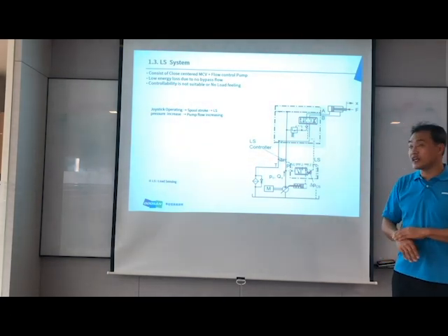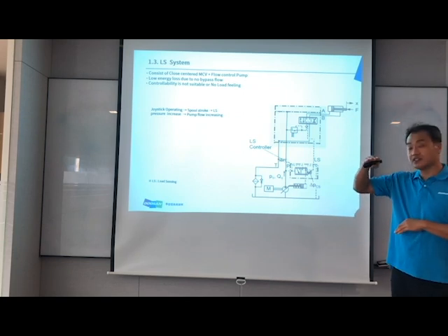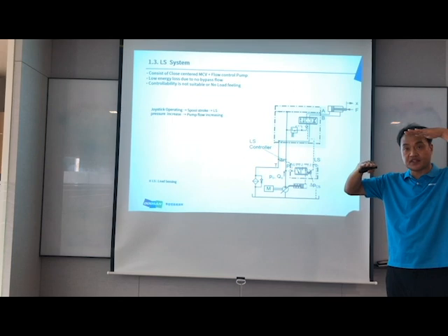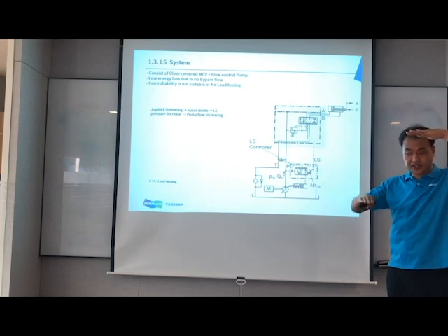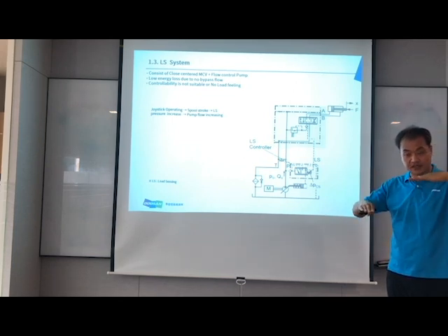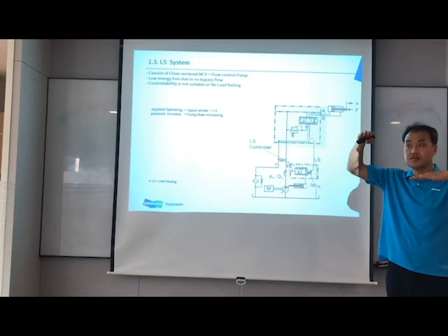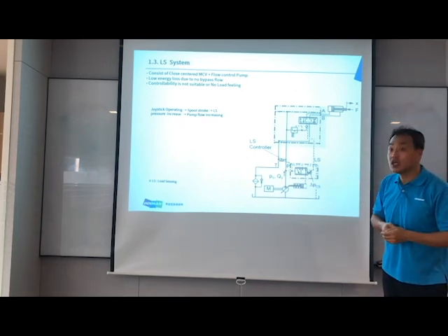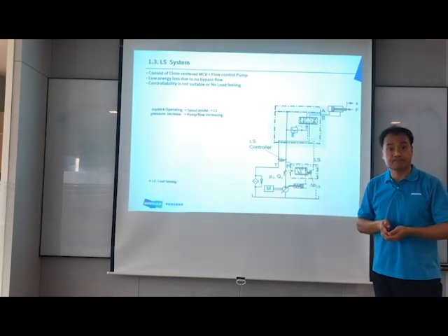Once again, in the LS system, the basic signal is LS, right? Load sensing signal. A specific value is always maintained. When cylinder pressure is like this, reduce flow like that. When cylinder pressure increases, increase flow like that. The 20 bar gap is the key point of the LS system. Alright?